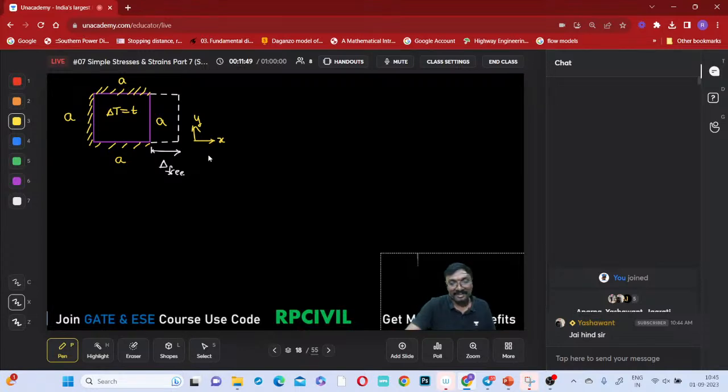Whenever temperature is rising or falling, if you just observe, what is the total epsilon x? Epsilon x is sigma x by E, minus mu sigma y by E, minus mu sigma z by E. We have to use this if there is a load applied or stresses applied.